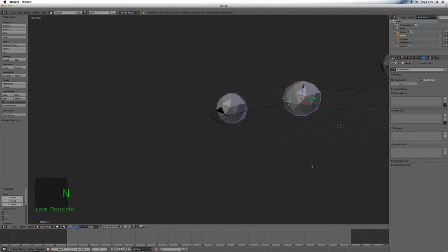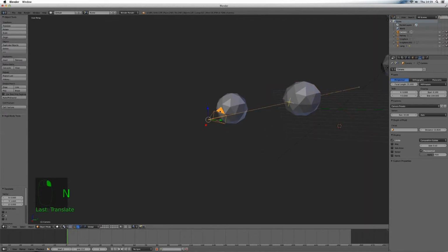And if I just get rid of that menu, go back into my camera menu, click on my camera, you can see instead of where it says focus, instead of having distance, so I can still move that around, I'm going to take that away and I'm going to click on Harvey. It has a list of every object in your scene, and Harvey's the one we want to follow. So the X is now inside that iconosphere. So we know that the camera is going to follow that no matter where we put the camera, no matter how much Harvey moves around, it will follow him. So there you go. That's the easiest way to do it.